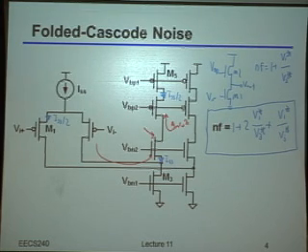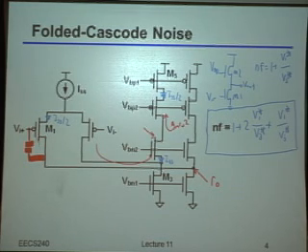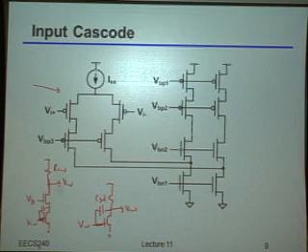gm, right? So if I now look at the source node, one cascode below it, how big is that swing? What's it proportional to? Yeah, it's proportional to just ro, right? That's still pretty high. Maybe it's not super high, but that could easily be a factor of 4, 5, 10. So if I really wanted to make sure that that Cgd, which of course would be sitting right here, does not experience a gain from this point to this point, I need to add yet another cascode, which is exactly what I've done in this picture right here.